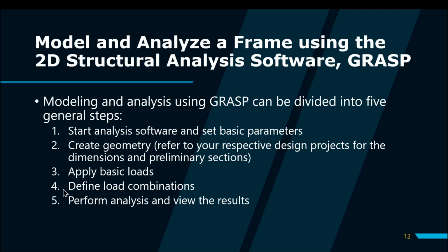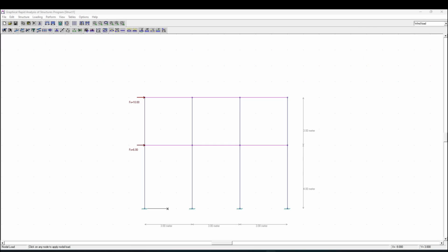Now we can proceed with the definition of load combinations. Here, first you define load combinations by pressing on loading and then add load case. This time click on this option, load combination load case, and then type here the loading combinations you're going to use.